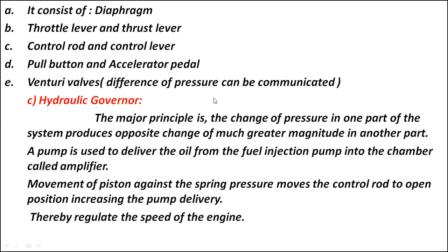Next is the hydraulic governor. As you all know the hydraulic principle, Pascal's law, the same is used in this hydraulic governor. The change of pressure in one part of the system will create a change in another part. The pump is used to deliver the oil from the fuel injection pump into the chamber.